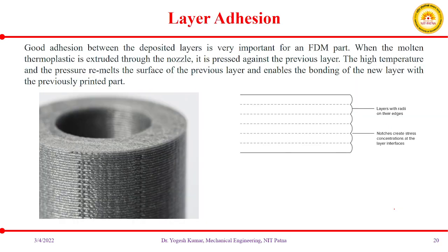Okay, so this warping can be reduced to an extent by proper adhesion as well as a smaller cooling rate. Okay, instead of a high cooling rate, we can adopt a smaller, lower cooling rate. Then this warping effect is reduced.